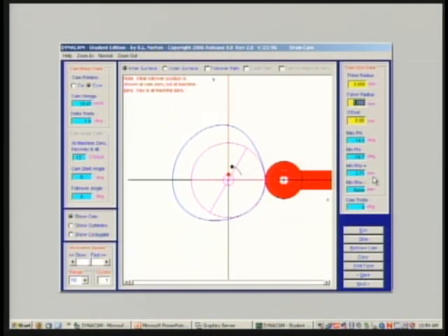That should be inches, because we're working in inches. So these labels have not been properly changed. Ignore those labels. They should say inches. So this is actually 2.71 inches. My follower radius is 1 inch, and that is sufficiently smaller than this 2.71.